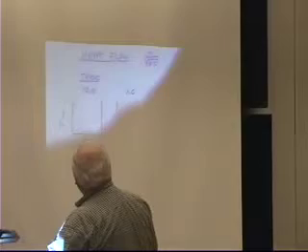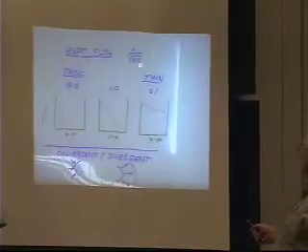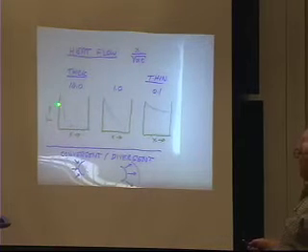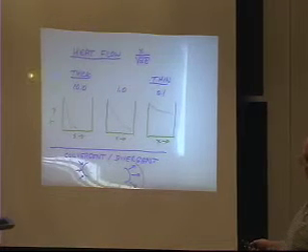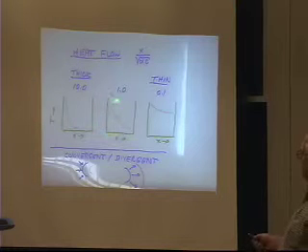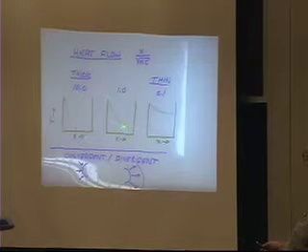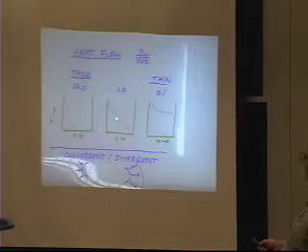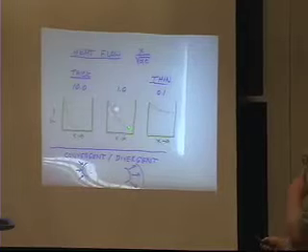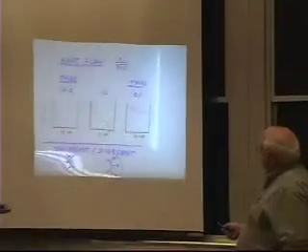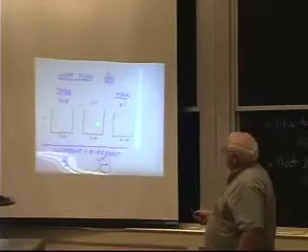Remember we talked about the Fourier number. If I have something that's thick, in a given amount of time the heat will not penetrate all the way through because there's not enough time for the temperature to rise all the way through. When the Fourier number is 1 and the distance and time are such that the temperature on the surface decreases to about 10% of its original value, that's the Fourier number of 1 for a simple one-dimensional solution.